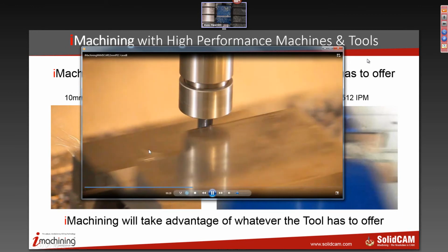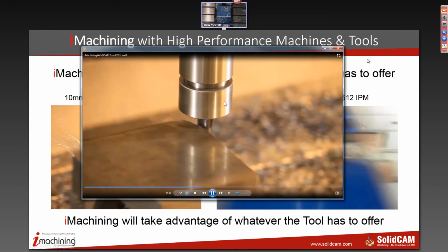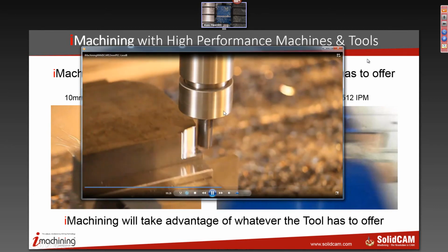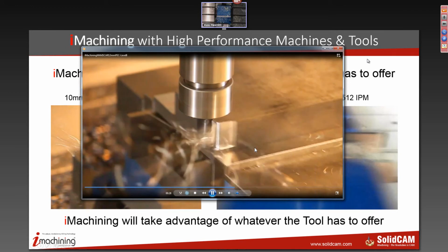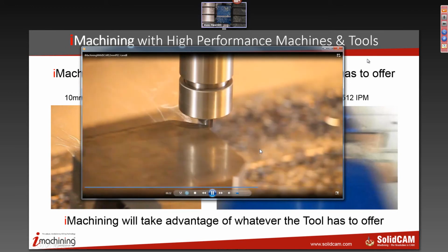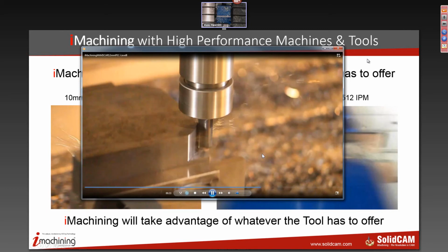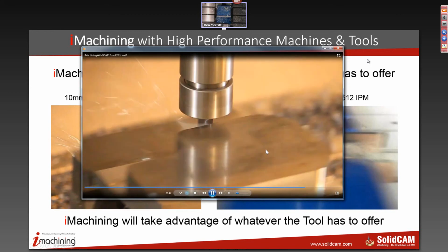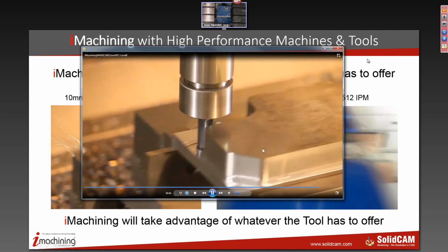And this is a high-end milling chuck, okay? This is not a cheap piece of equipment that I bought. We got a really good milling chuck trying to hold on to this cutter. But watch what happens right here. See that line up here? I mean, we're boogieing. We're at super high performance on this. Pulling the tool out of the tool holder, okay? So you've got to be careful when you're doing this stuff.